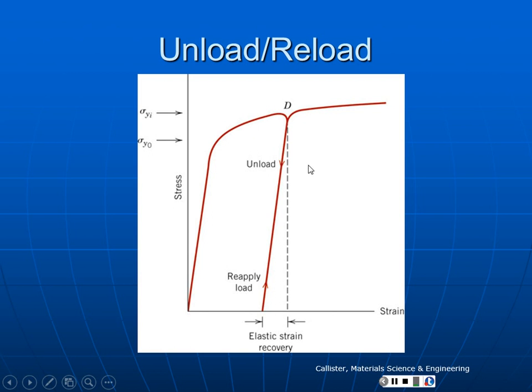All right, this points out the fact that when a stress strain curve is sloped upwards after the yield, the material is actually getting stronger. It is taking more and more stress to continue to deform it. And we call that strain hardening. We'll be looking at how that happens or why that happens in a couple of weeks. But that's what's going on when the stress is rising on a stress strain curve.